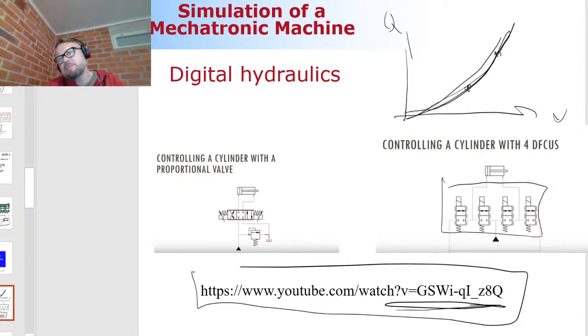It is mentioned that digital hydraulics is good because then you can get rid of the control based on the pressure differences. That's not entirely true, but there is some huge potential related to this, particularly if you can control the pump using the same concept as valves. It means that in a piston pump, you make a decision every time the piston is moving whether or not you're producing energy to the system. That would be very nice energy-wise, and energy is a big deal today. So we need to get back to digital hydraulics when we are discussing the pumps.